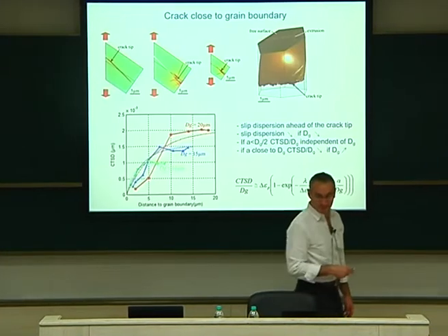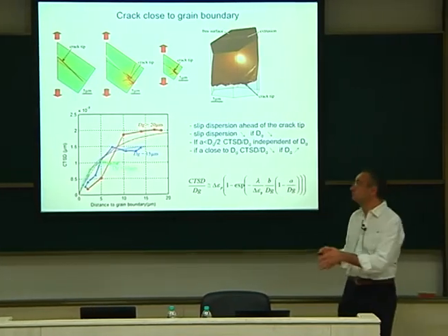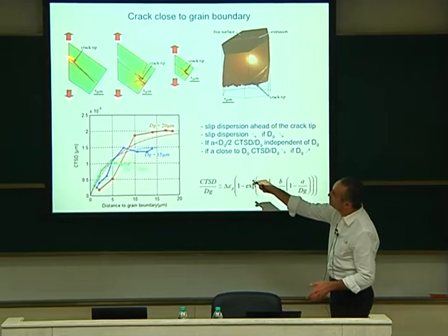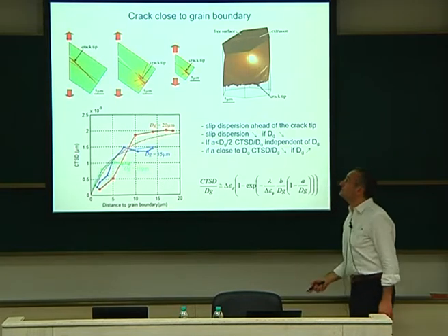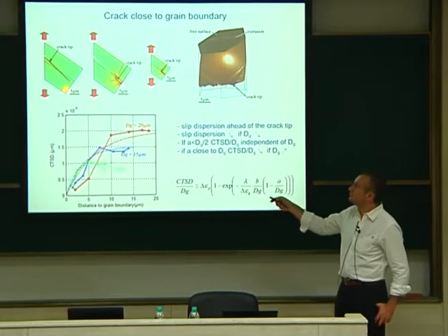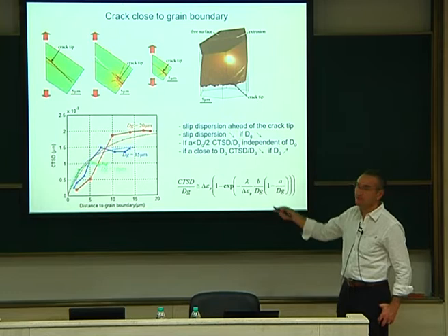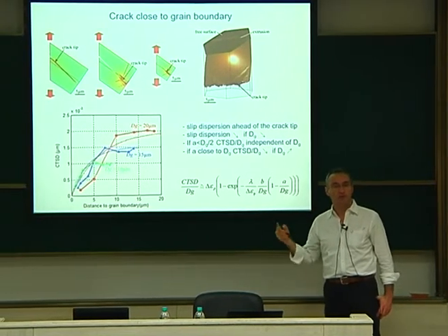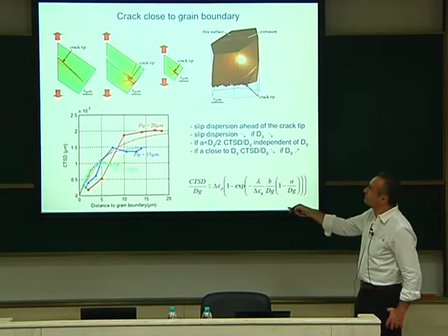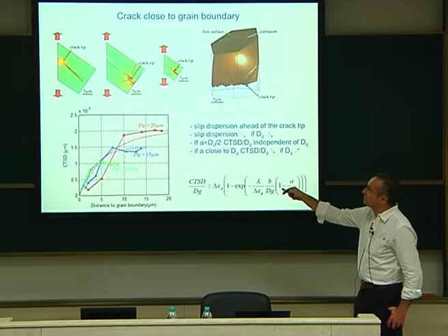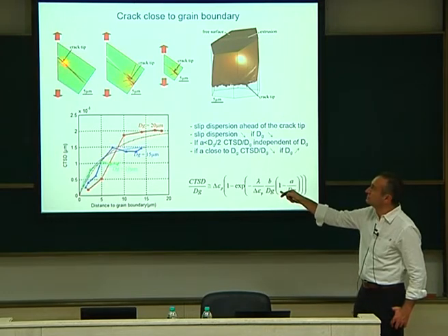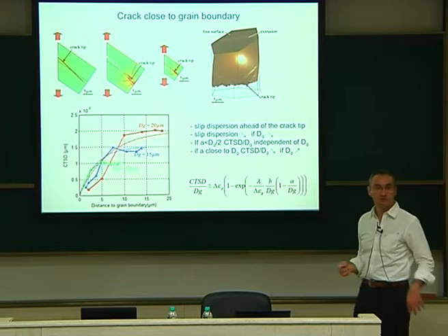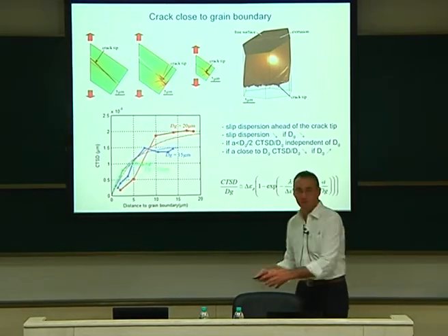Okay. So now that we know the crack would advance at this place here, on the obtuse place compared to the persistent slip bands, we were investigating the position of the crack compared to the grain boundary. So this is the grain boundary, this first microstructural barrier, as I said. The crack is here, and now it is there. Okay, this could be different. What is the difference between this position and that position? Just to see if the crack propagation is always the same during the grain.